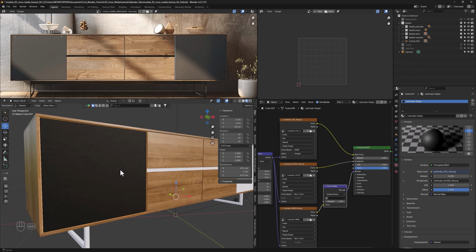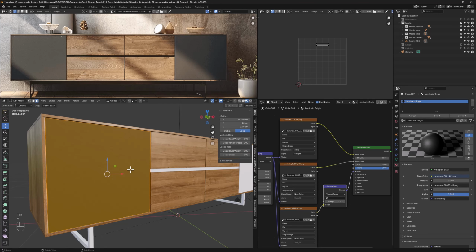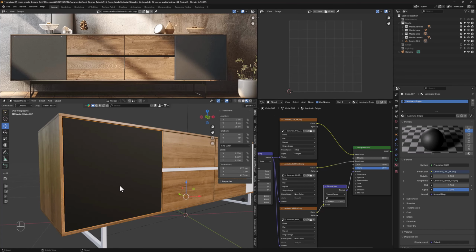By observing the door panel model to check the result, we notice that the texture surface doesn't look correct and shows some irregularities. Let's switch the working mode to edit mode and select the entire geometry. There is no mapping present in the UV editor. In the perspective window, press the U key and choose Smart UV Project Unwrap. Let's return to object mode and check that the texture now displays a significantly more uniform surface.